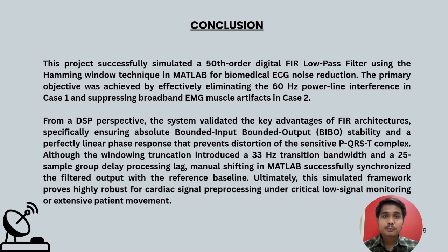So, to wrap up this project, we successfully simulated a 50th order digital FIR low pass filter using the Hamming window technique in MATLAB for biomedical ECG noise reduction. As you can see from our results, the primary objective was achieved. We effectively eliminated the 60 Hz power line interference in case 1 and suppressed the EMG muscle artifact in case 2. From the ADSP perspective, why did we choose a FIR architecture? Because it ensures two main things: absolute BIBO stability and a perfectly linear phase response. This is extremely important to prevent any distortion on the sensitive PQRST complex.